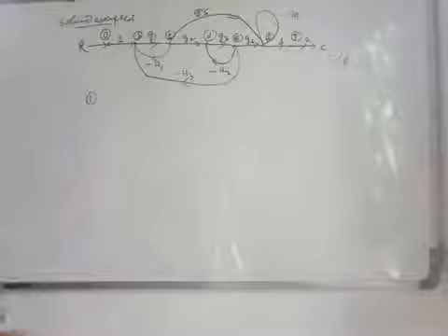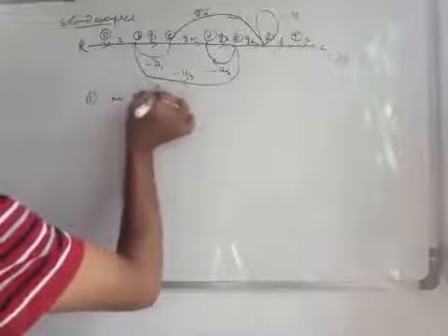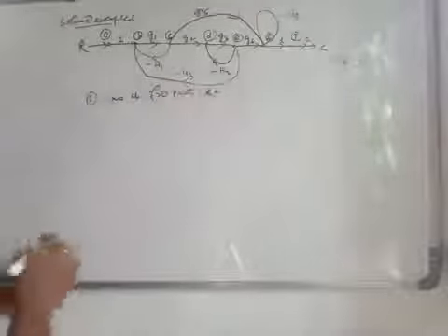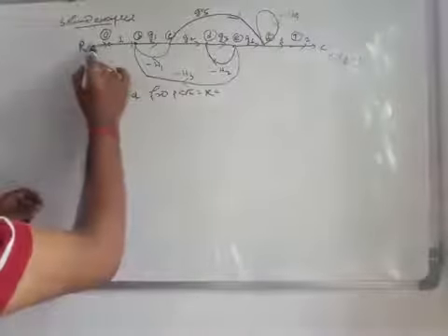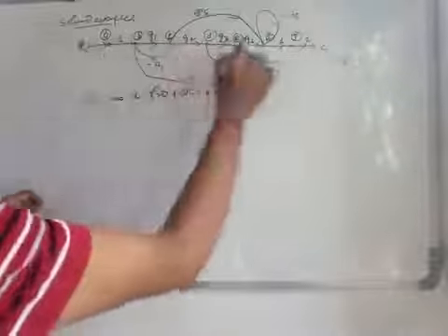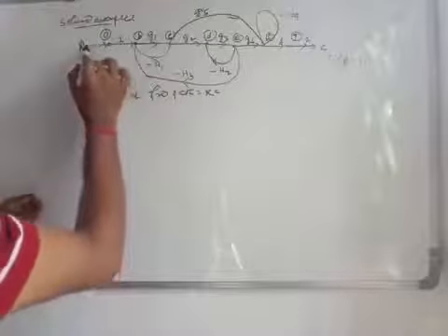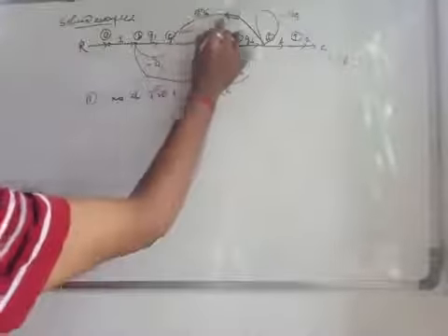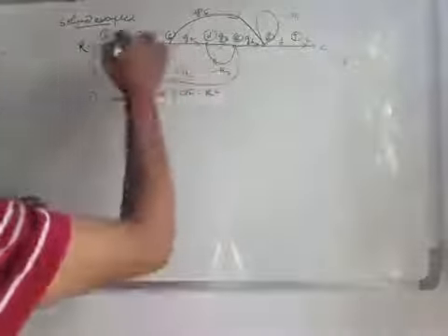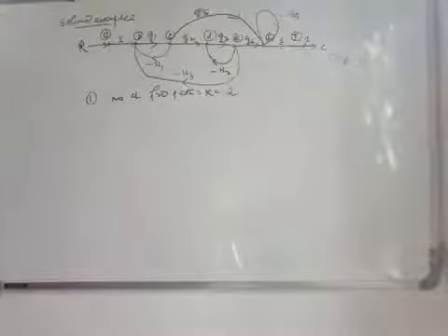First of all, what you have to find out is the number of forward paths, that is K. Try to find the arrow directed from R to C. So this is one forward path, as you see. Next, you move from there and go there. So this could be another forward path. So definitely there will be two forward paths.